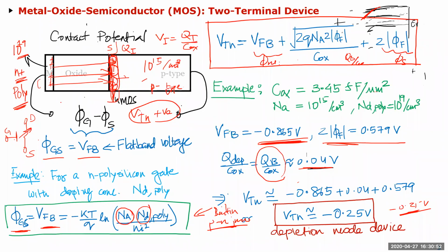Okay, does everyone follow this, or any questions? Yeah. In the Kang book, it has been written that the VT can be increased in case of NMOS by doping with p-type impurities, Na, right? Because VTH is proportional to the square root of Na in the above equation. Yes, that's a good point. So if you see here, this is Na, which is this dopant here, right?